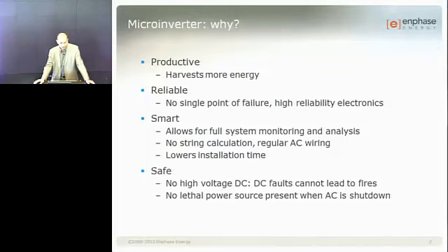Something which is interesting to understand as well is that the power electronics in there operate at a much reduced power level than a regular large inverter. If you have a megawatt inverter, you'll be dissipating 30 kilowatts in the inverter. It's a big amount of power, and the box is big, but not that big, which means the density of power dissipation is very high. In our box, we dissipate 5, 6, 7 watts in a small box, and it's much easier to do. We don't need any kind of forced air cooling or water cooling like big inverters have to have. So it's also much simpler as far as power dissipation.